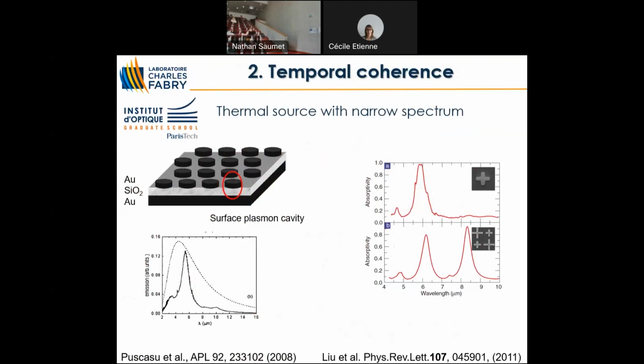So even though there is not much glass, because you are introducing resonators, now the field is large and the absorption is significant. By having a periodic array of these, as before, you can have a huge absorptivity. And this absorptivity happens at a single frequency, which is the peak resonance of this resonator. That's the measurement in the far field.